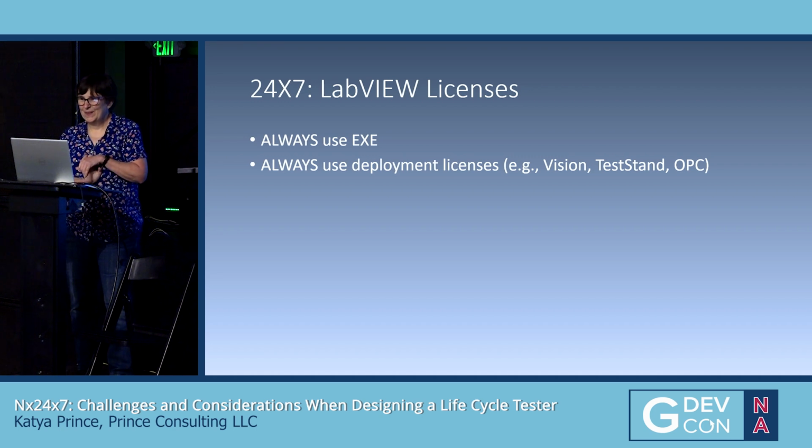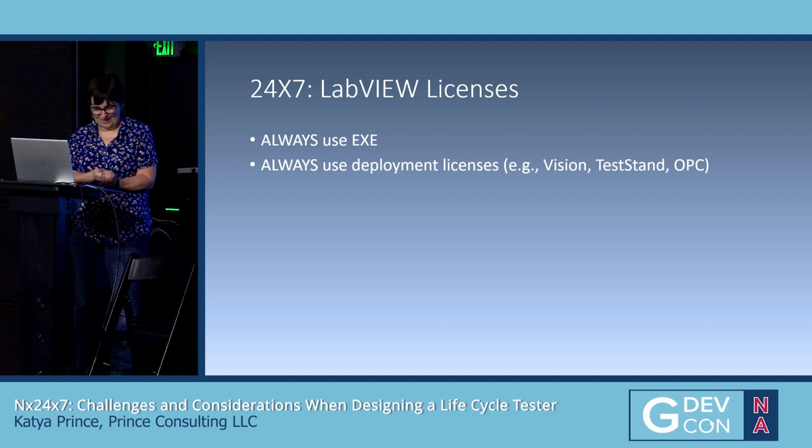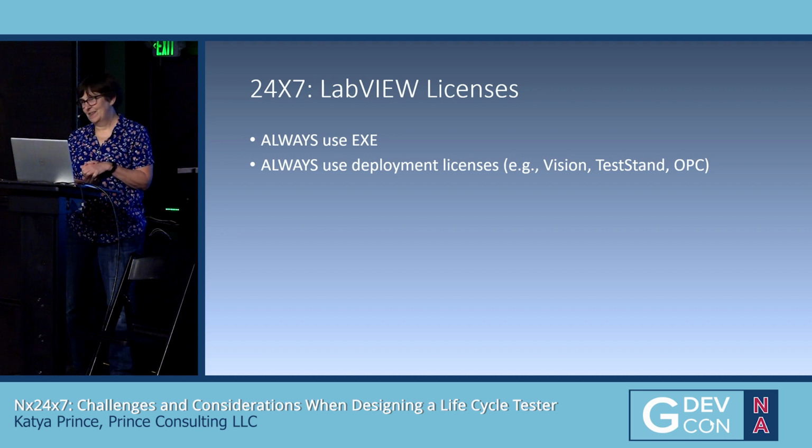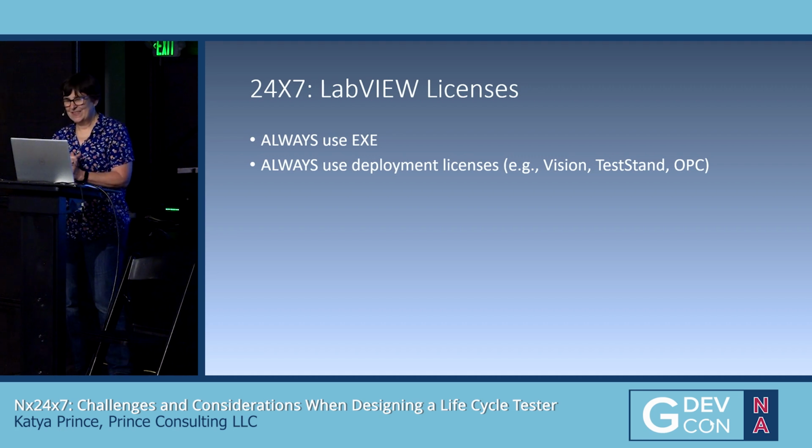The next thing I'm going to talk about are LabVIEW licenses. And this is, again, talking from experience here. Be sure you use an EXE. Do not leave them with a VI, with your subscription that expired in August, and then they rebooted the computer in November, and now the application doesn't work because the license has expired and needs to be reinstated.